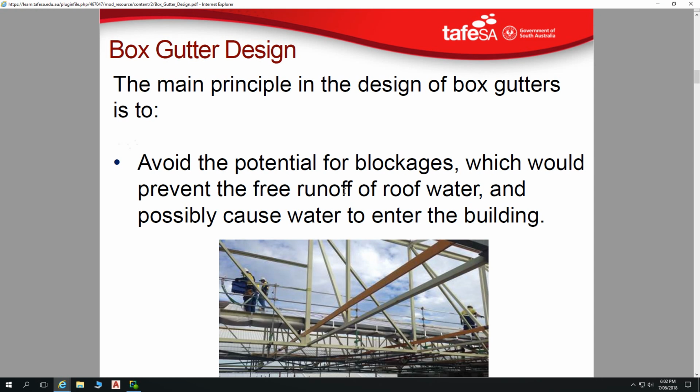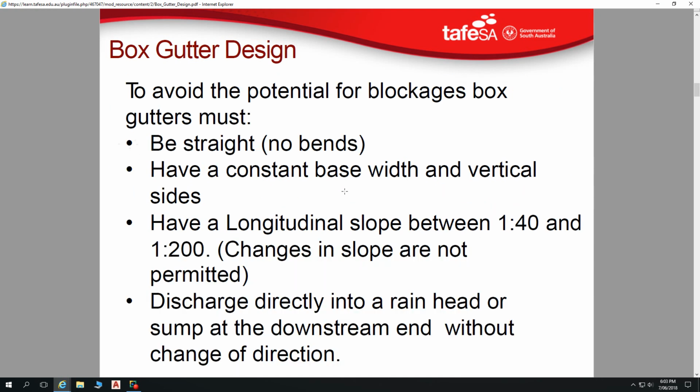So you don't get the obstruction of bits of hay and all sorts of debris. So it's a very safe way of exiting a box gutter. The whole end of the box gutter is open. And I think it doesn't actually look too bad. It's something I wouldn't be too averse to having included on a residential project either.